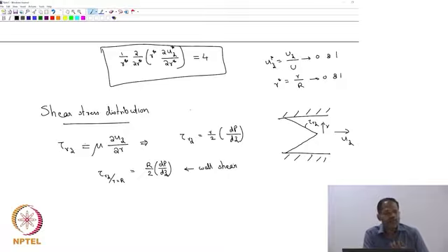Okay. So typically when you want to talk about a force that is resisting your fluid motion, it is really the wall shear. Now, that is true in case of a laminar flow, and this is a quantity that is going to change when you talk about other flows like turbulent flow, or we will see a few more examples later, but wall shear is actually an important quantity. That is also clear.